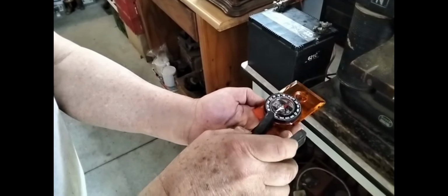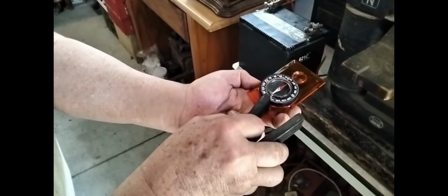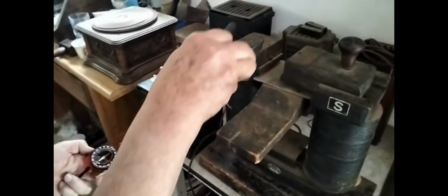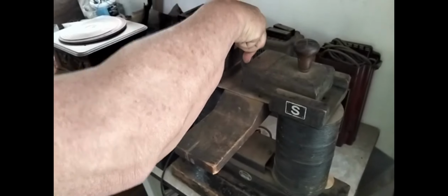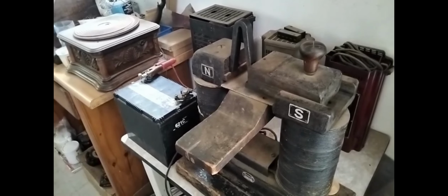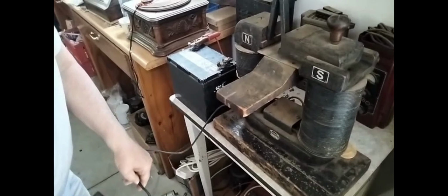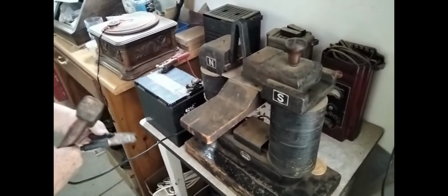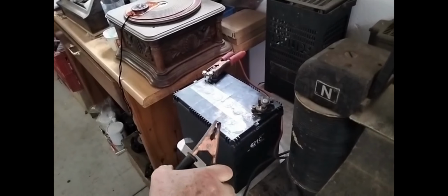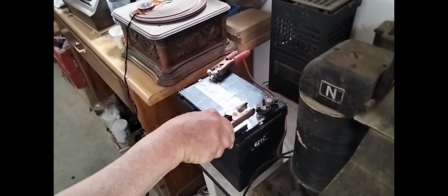And I have to pair the north pole to the south pole, or alternatively the south pole to the north pole on the magnetizer. So the magnetizer is marked, and I'm putting the south pole on the north pole. So now I'm going to apply voltage to the magnetizer. I have a car battery set up here with terminals on it so that I don't damage the terminals of the battery. And as you'll see, you get an arc.